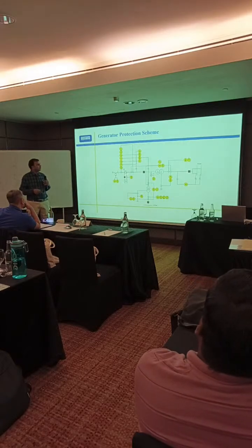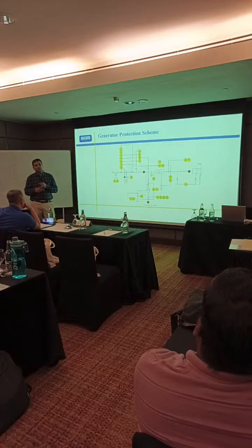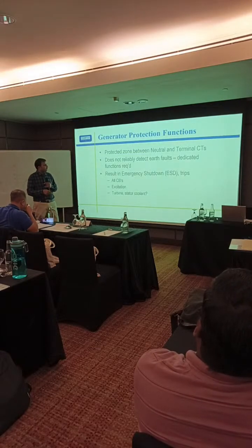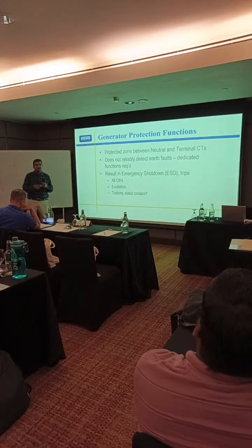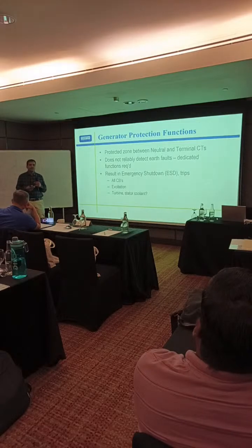So right now you just understand the reason why it is there, why this line is written. You can understand because of the ground impedance. In the transformer case, it is solidly grounded, so the earth fault condition will be detected very easily.